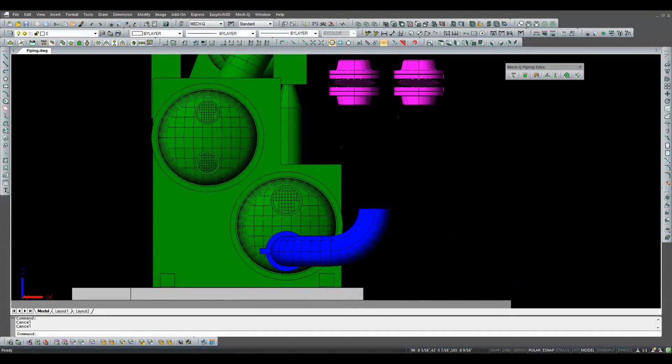I've switched to an elevation view and reinstalled the second elbow on the chiller and locked its face up. Let's slide it to align with the butterfly valve above that it will eventually be connected to. For any 3D object such as this elbow, all we need to do is pick 3 points to define it. As we saw earlier, the first point can be anywhere on the slide axis, but the second point must be the focal point. For the third point, we'll pick the remaining face of the elbow. For the point to align with, we can pick any point on the center of the associated butterfly valve. Now we see the elbow slides into position.